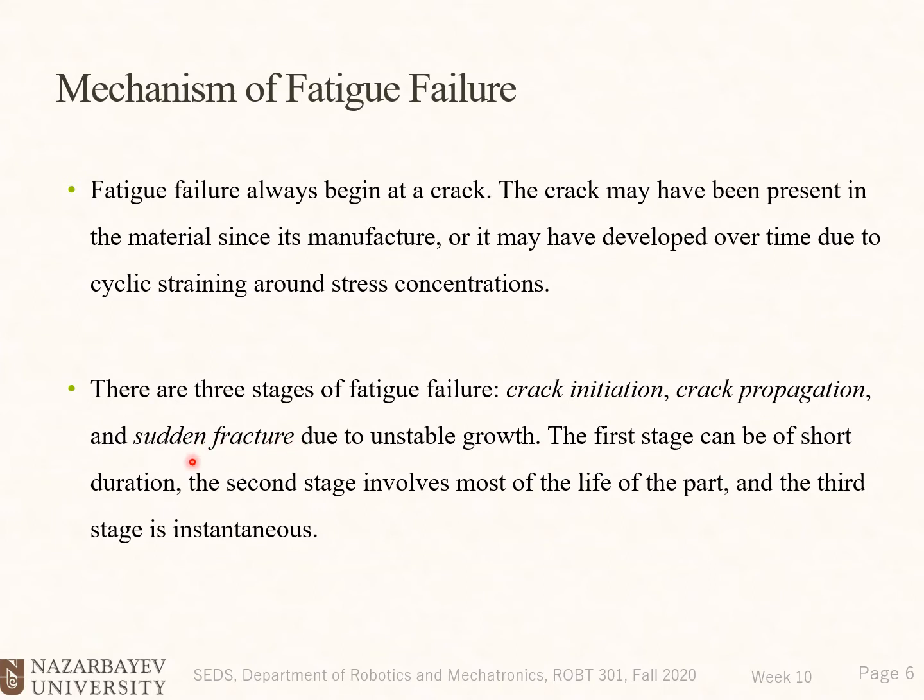Yes, and you've seen that, for example, for windshield of cars, we have first a small crack starts to grow, and then suddenly one day in the morning you come and see that, wow, the crack grows and now covers all over the windshield. Okay, and this is the same kind of mechanism that we have these three stages for the crack and in the fatigue failure.